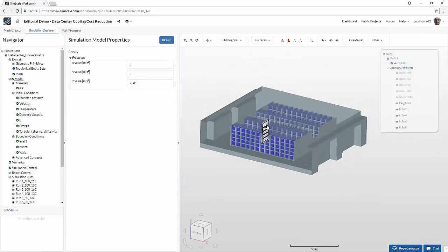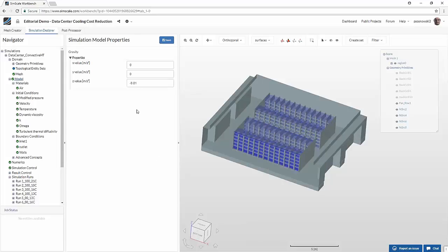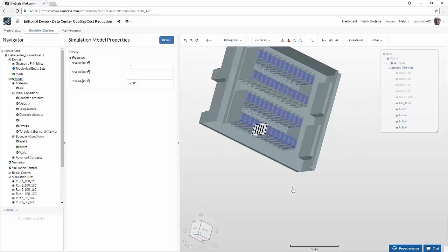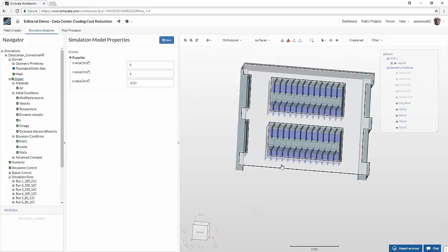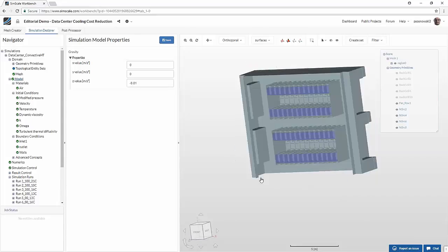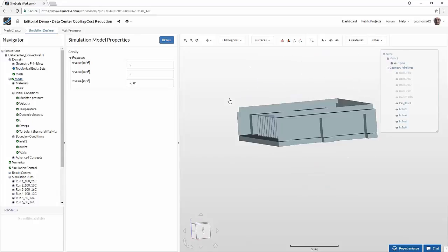One thing that many people tend to forget. I used to do this a lot. And one question that I always get is, why do we have to set up gravity? It's always pointing downwards. Well, an obvious answer is that sometimes people decide that Z minus is downwards and sometimes it's Y minus. I recall once running a simulation of air convection within a room where gravity was pointing in an X positive direction, and I misplaced that. The results were pretty interesting, let's put it that way.